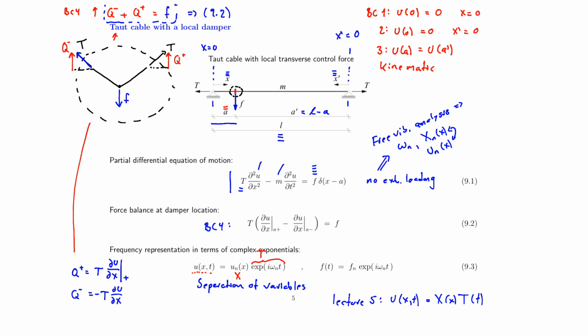And we had something similar in lecture number 5 for vibration analysis of beams. In that case, for beams, we didn't assume a general expression for capital T. We assumed a cosine representation of the temporal part, that is the T function. In this case, we do it more general than the cosine, but more specific than a general T, namely a complex exponential function. But this complex exponential function still represents harmonics by the real part.